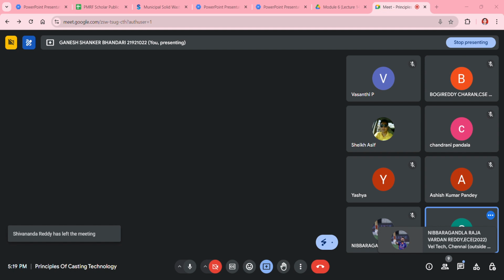And we have a collection vehicle capacity. Here we have to consider this also. Collection vehicle capacity is 23 meter cube per trip. One container size in the stationary container system is 6 meter cube, and container utilization factor is 0.67.